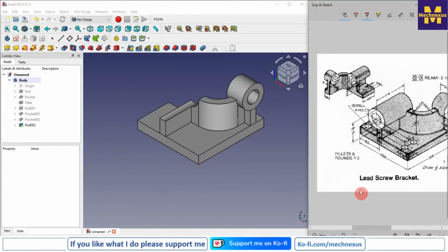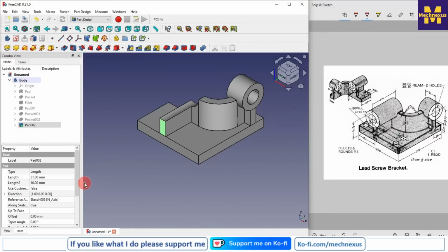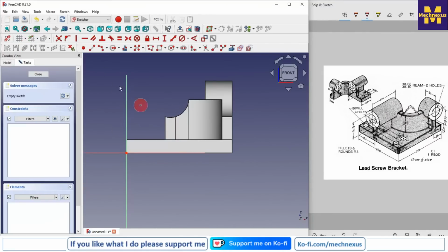Now we will do the same for this type, which we have created a cut here. So we will do the same procedure, select the face and create a sketch, and now we will project the geometry. So I will select this edge and we will get the center mark here. Now click on the circle tools and again click on the circle.